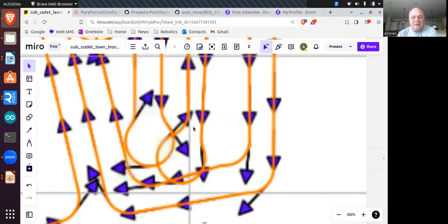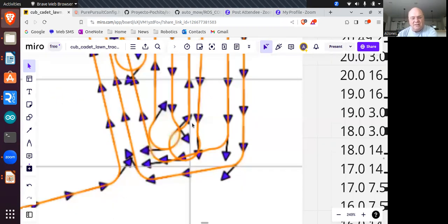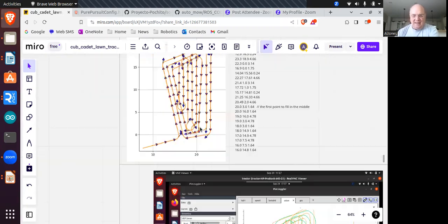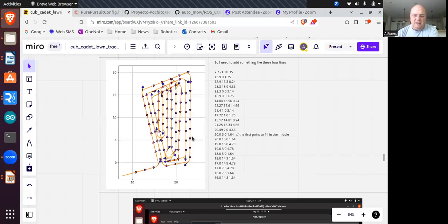And finds its way back up there. So it gives a really, well, poor steering. So that led me to the path of trying to mix these 90-degree turns that seem to work reasonably well with the look ahead of 2.5 to the point of, well, maybe I need to be able to have both, to change the look ahead based on the waypoint as well as the speed.